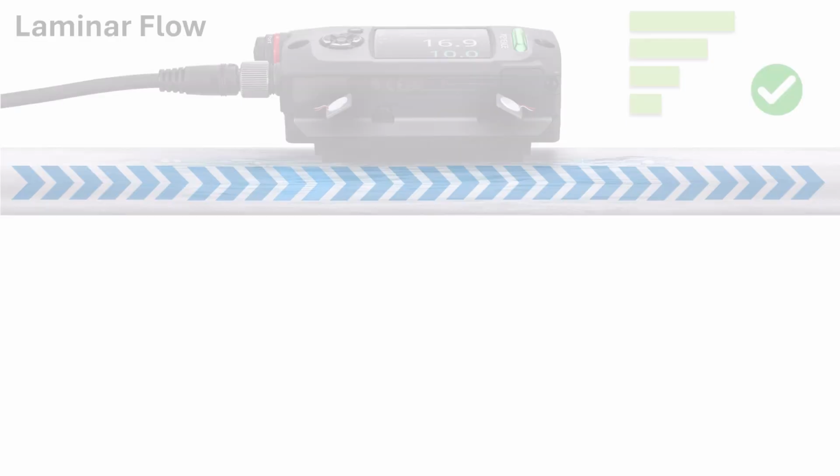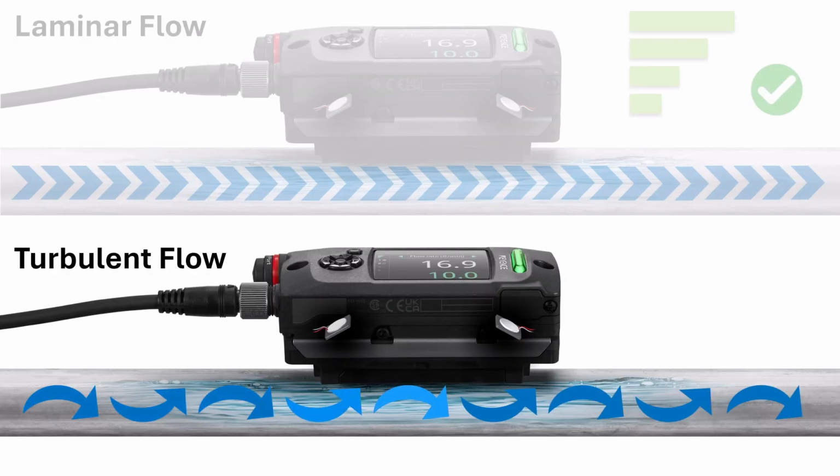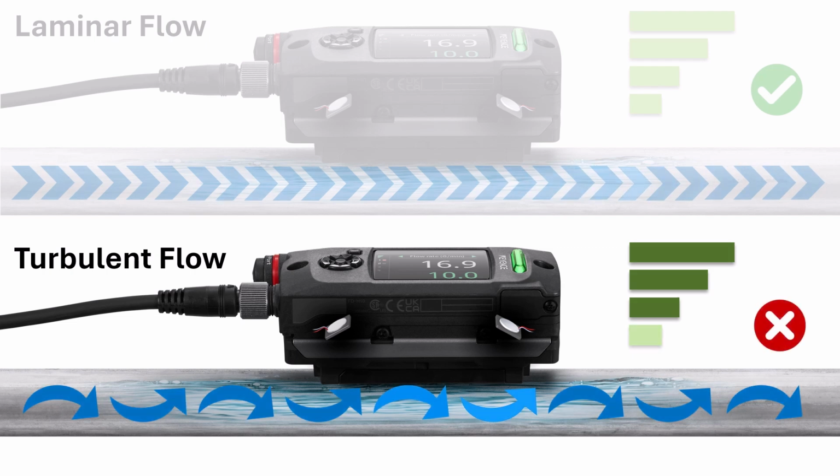On the contrary, if the liquid is turbulently traveling through the pipe, the ultrasonic waves will be affected by the chaotic movement of the liquid and may not be received by the flow meter, leading to low stability.